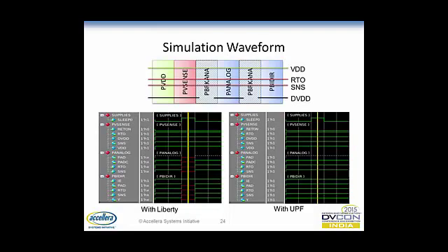In the first waveform, if you see, Liberty doesn't provide this capability. So when analog power is down, it corrupts all the control signals, resulting in corruption of the signals in the bidirectional cell. But with this particular approach, I'm able to guide the tool, saying that these signals are floating or feed through, and because of that, it doesn't corrupt those signals, so I'm able to simulate the correct behavior of the bidirectional cell. Using Liberty right now, we cannot solve this problem. That's when the successive refinement flow will help, whereby we provide separate UPF models for this.